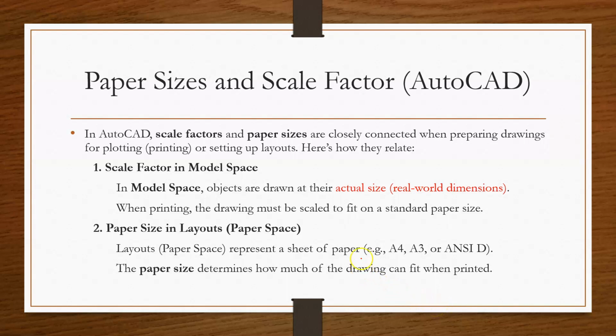But I want you to understand that anytime you're drafting in AutoCAD inside the model space, this is the important thing here, always, always, always draw it to the real world sizes. If you get something out of this and you go to a job or something of that nature, don't tell them that I told you, hey, he said don't draw it to the real size here in the model space. No. What I'm telling you is that you got to actually draw it. Now, there is an exception to this, and I will try to demonstrate that when we get to the example here in AutoCAD.